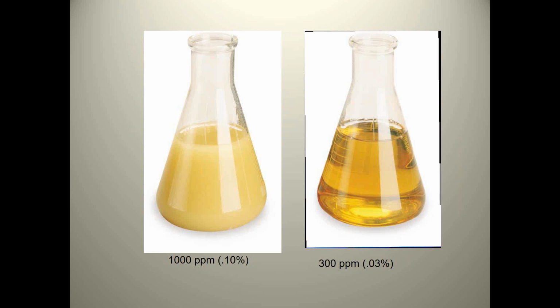But if it stays like this, turns into a slushy, then that oil's went through a change. It's not really a good lubricant anymore. It's went through that process of hydrolysis, and it'll stay foamy and milky looking like this. So in this case, you need to change the oil.